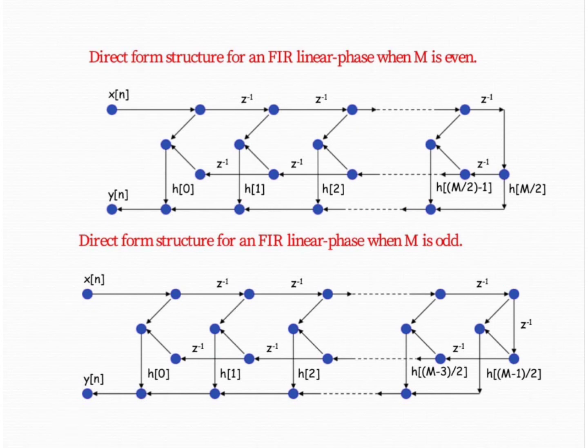Whatever the transfer function, we can implement it like this, because as we connect two individual delay functions with a single multiplier, we reduce our multipliers by using the linear phase property of the FIR system. With the linear phase property, we generally reduce the multipliers used for the implementation. Whatever the multiplier, if it is common to individual delay function parts, we consider one multiplier, with the help of which our implementation cost is reduced.